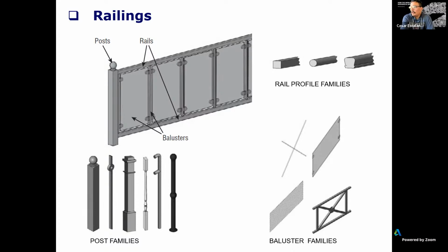A lot of the railing parameters are type parameters that define the distribution of the different posts, the distribution of the railings in the horizontal, and the distribution of the balusters. So a post is a representation of a railing post. It's a solid created using the solid editor.